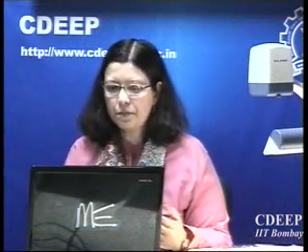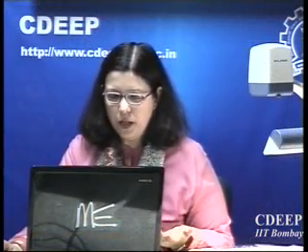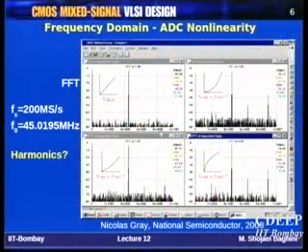Suppose, I don't know how many he has chosen, but I think it is around 8,000-point FFT. So 8,000-point FFT divided by 2 will be around 4,000. Therefore, if you want to get your frequency bin, it will be 2 pi divided by this number, and your power will be divided by this number, because now you assign a particular power to every frequency bin. It's power spectral density.